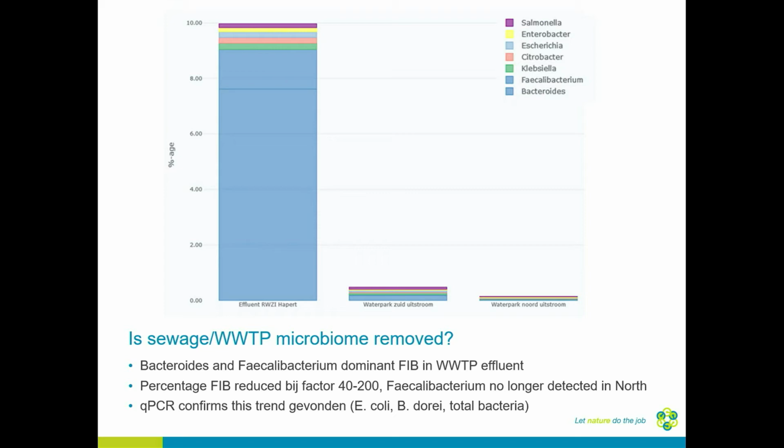Another thing that was quite interesting, as you can see, the first one is the southern discharge point seemed to have a slightly lower reduction rate than the northern discharge point. And it was actually noted while they were taking all these samples that there was a shortcut circuit in this part of the constructed wetland, in the southern part. So some of the water wasn't going through the whole constructed wetland. And we saw this in a lot of the results, that the removal efficiency of this constructed wetland was, in fact, a lot lower than the northern side. So this also helps to demonstrate how important it is to upkeep the constructed wetland and make sure everything's working correctly. Because if it goes through everything, in the end, you remove a lot more.